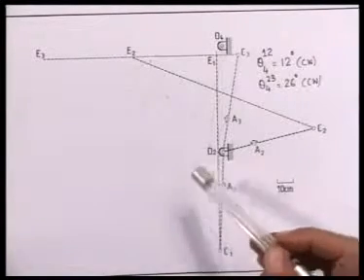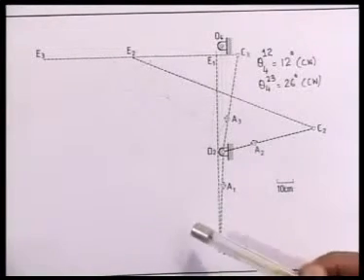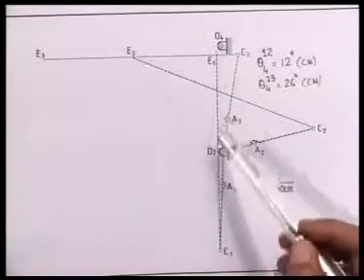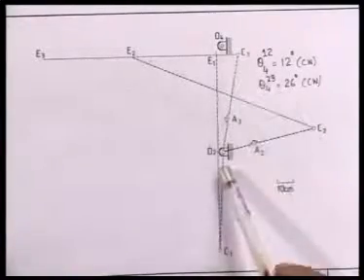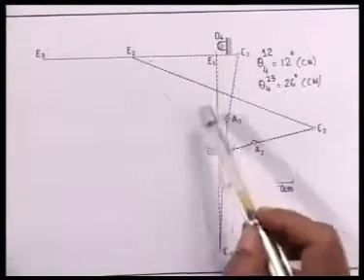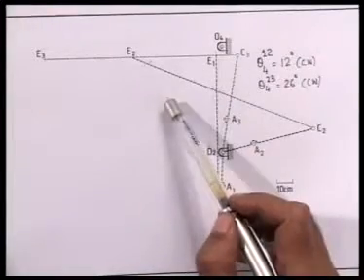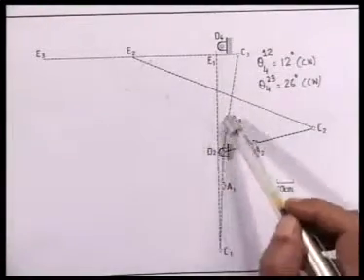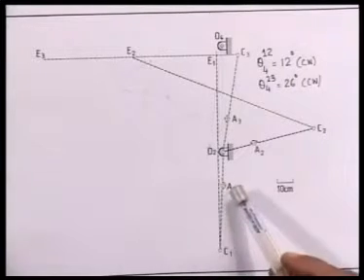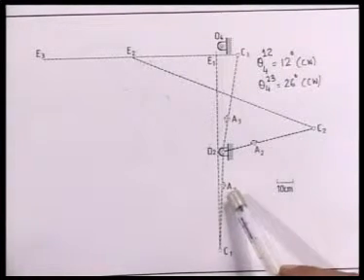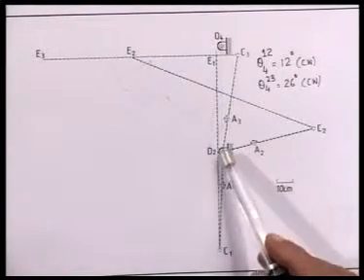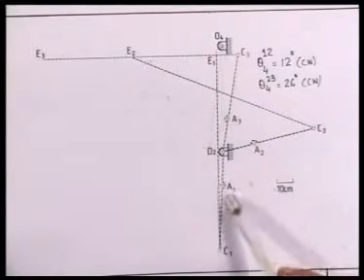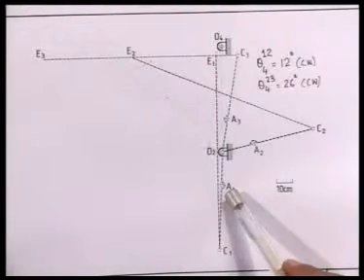We achieve this design in 2 stages. First, we design the 4-link part of this mechanism, namely O2A, BO4. To obtain this 4-link mechanism, we conveniently choose the location of A, the hinge on link 2. A1 is chosen arbitrarily.